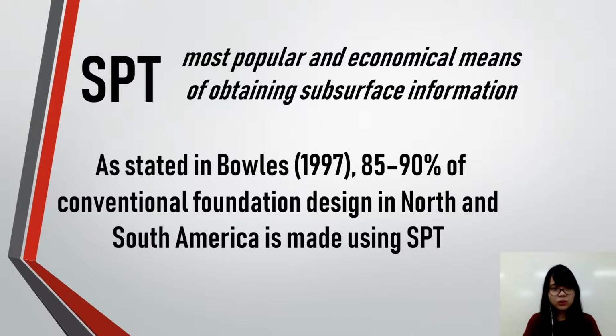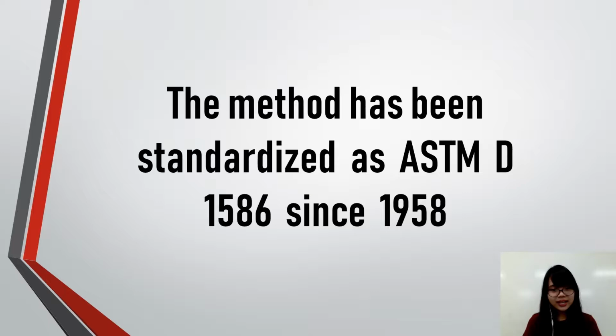It is also the most popular and economical means of obtaining subsurface information. As stated in Bowles, 1997, 85 to 90% of conventional foundation designs in both North and South America is made using SPT. The method was standardized in 1958 as ASTM-D 1586.